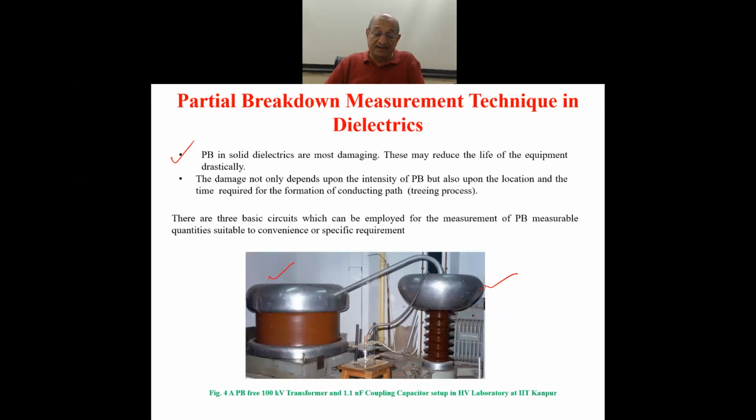And they are connected not with just a simple wire, but with the help of a pipe connection. Why pipe connection? When you increase the dimension of the conductor, the field intensity goes down, and that would require very high voltage for the partial breakdown around the conductor to take place.